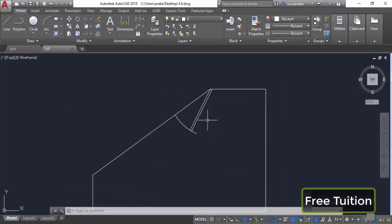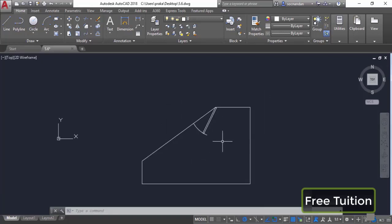Now in this case you can clearly see that the first point is here where we clicked. The second point was the midpoint, and obviously I said that by clicking the midpoint we are essentially assigning this line as the second point. So here the second point has been assigned, and the third point decided the direction, whether inside or outside. And here we have it, the object not only moved but also properly aligned according to the geometry. And using this tool you can also align similar kinds of geometries on different objects. So that was the align tool of AutoCAD.